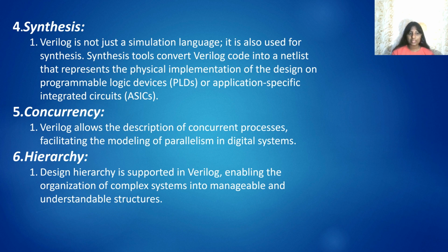Then the fourth one is synthesis. Verilog is not just a simulation language, it is also used for synthesis. Synthesis tools convert Verilog code into netlists that represent the physical implementation of the design on programmable logic devices, PLDs, or application-specific integrated circuits, ASICs. Fifth one is concurrency.